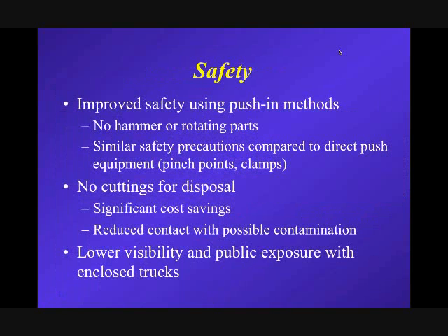And one of the advantages that CPT has, of course, is improved safety using pushing devices. There's no hammer, there's no rotating parts. You have the similar sort of safety precautions of any direct push equipment. The other advantage is you have no cuttings. And in California, if you are drilling on a site that has potentially contaminated soils, you have to dispose of the cuttings, and that adds a significant cost to drilling.